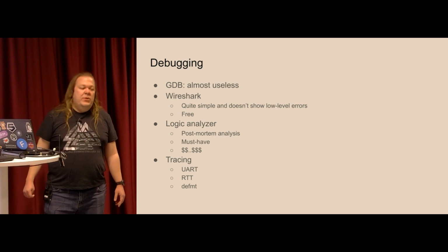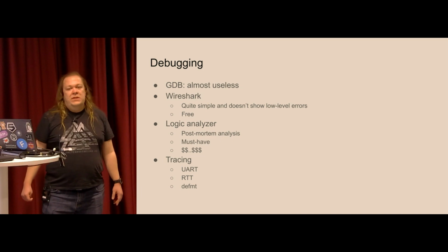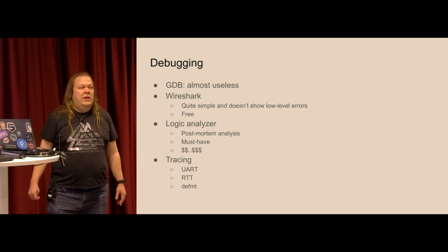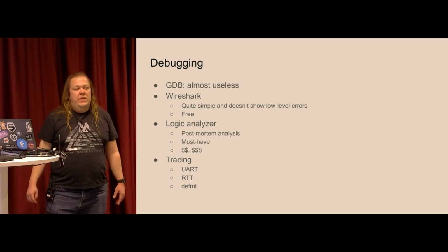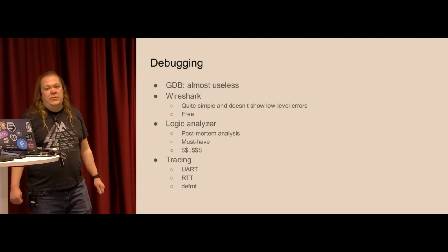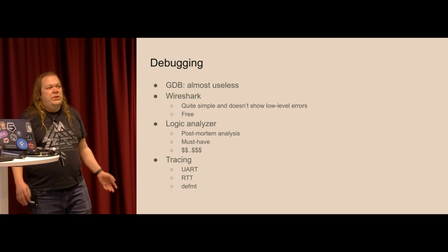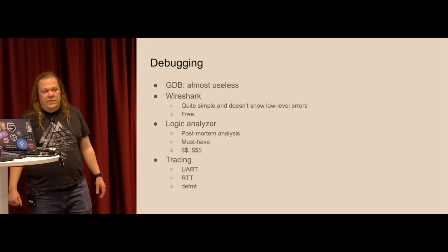Then we have the most important tool here, logic analyzers. A logic analyzer is dedicated hardware which can gather bits from your wires. And usually you can store quite a lot of data before you analyze it. So for example, the logic analyzers which I show later are capable of storing data in real time, so you can store as much data as you can fit on your hard drive or SSD.